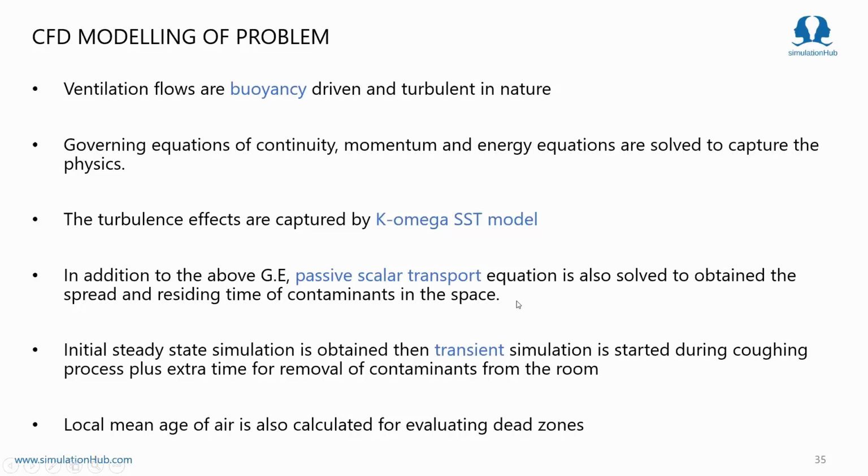Just to give you more information about the simulation, we perform the simulation in 2 stages. In the first stage, we perform the steady state simulation to obtain the flow pattern in the room. And then on the same setup, we started the transient simulation for the time including the coughing time, plus some extra time to see how the contaminant is distributing and being removed from the space in different scenarios.